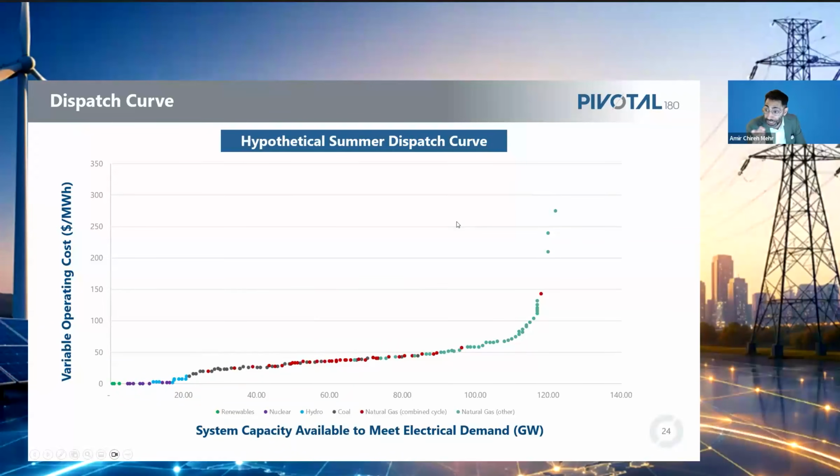We looked at the full day's worth of demand, but as I said, in electricity, demand is instantaneous. If in the morning peak at 9 o'clock, when everyone gets up, they turn on their TVs, they run their electric kettles, you're microwaving something, maybe to heat it up for a pet, you're going to need 93 gigawatts, rain or shine. Even if there are dispatchable resources like battery storage or pumped hydro, at that instant, you need to deliver the 93 gigawatts, whether it's coming from immediate generation or stored energy, as the case may be, right?